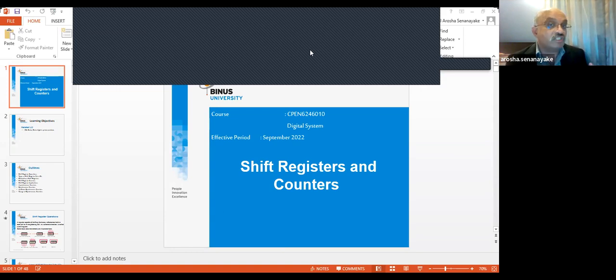Of course, you can use a JK flip-flop as well. Like this, in this case, we have 4 bits. Here also 4 bits. So what is the meaning of shift registers? Or how to shift? For example, if you have 1 here, how to move this 1 into the next, subsequent cell, and so forth to produce an output. That's more or less what we call shifting.